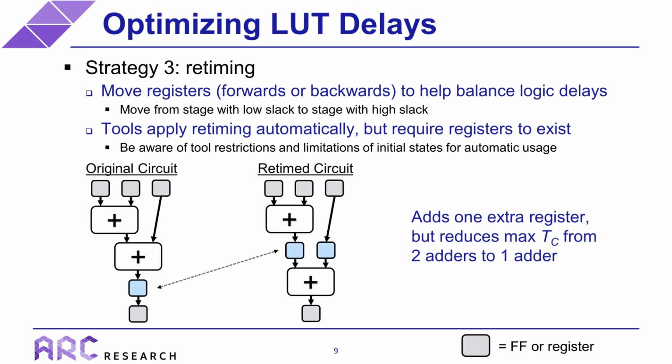So automatic retiming is still very useful though, because you can use it when either you don't know where the registers should be, you don't know their best placement, or when you just have too many registers and it's impractical to figure out and retime them yourself. Or there's simple situations where it's just awkward to specify certain locations for the registers, like in the example we saw on the previous slide with the comparator.